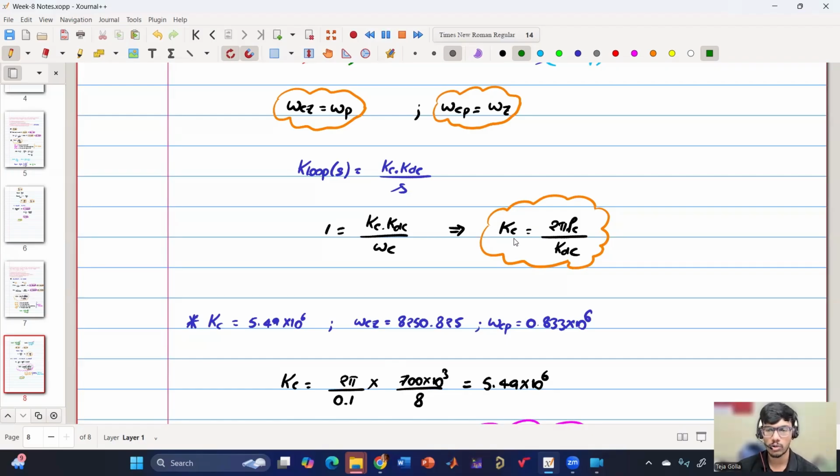If the gains are too much, it may lead to instability under certain cases, like if you consider digital control. The digital implementation will pose some limitation on the bandwidth that we can achieve, and it can cause instability. So in those cases, very high gains are not implementable and the system may not be stable. So we need to go for reduced bandwidth. Theoretically, we are dealing with all theoretical calculations, so there is no such issue in theory.